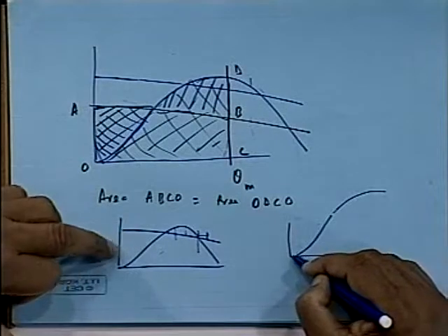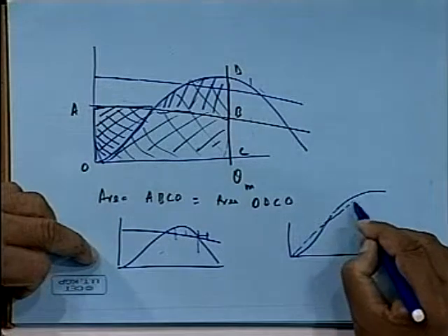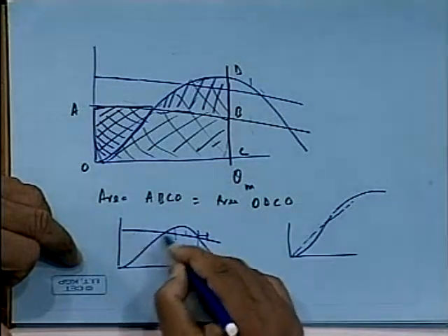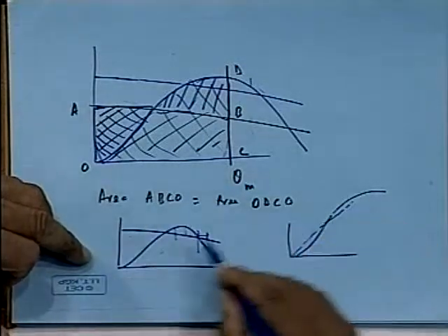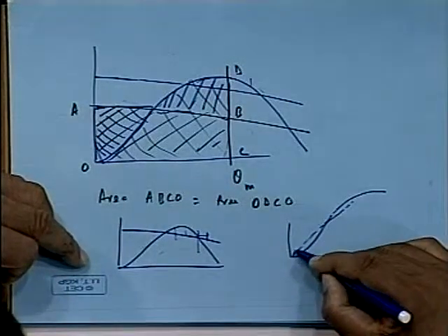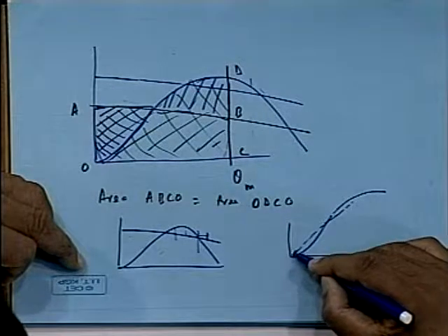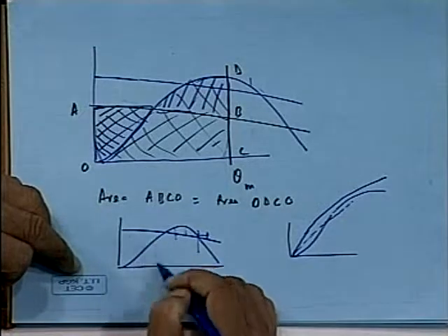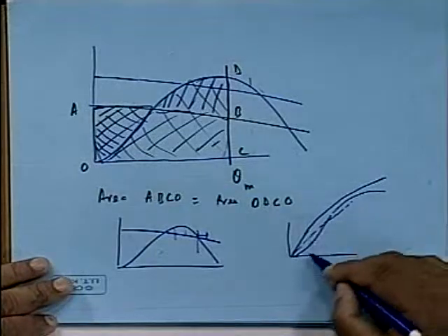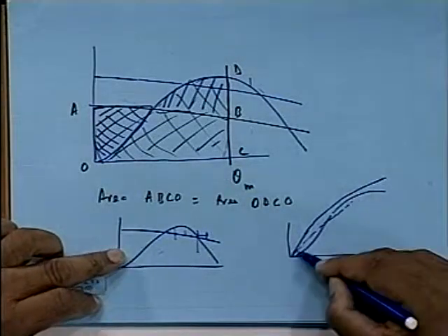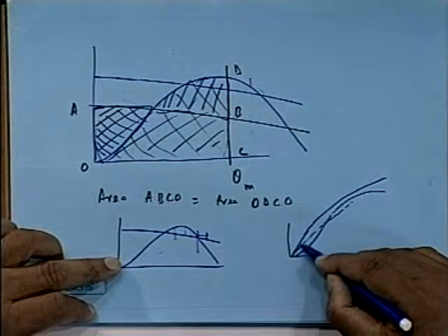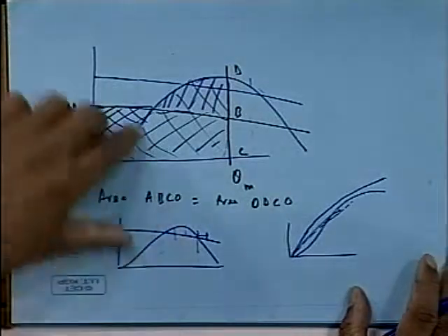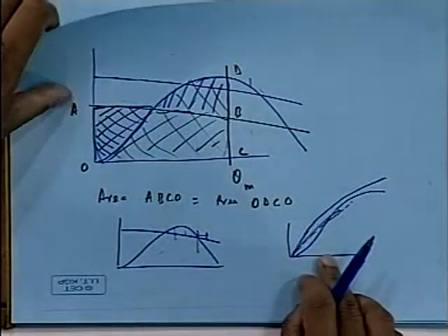See, the area under that was something like that. If I see the area under this, the full thing, it is always becoming more here, because at any point here the area is more. This is what is happening: if the wind heeling moment was too large, it never cuts. If it was not large enough, it would have cut at some point. So this is the curve you are drawing for the area. Now I'll explain that in the next one slightly better, because this may be a little confusing here.